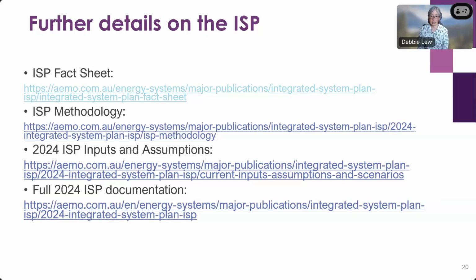That's right. So when we have our subregions and those interconnector paths, when we pre-calculate what the limits and the flows are, and when we apply an upgrade, a lot of the time it won't be a single number. We will actually put a constraint in there where it's not as radial or is more mesh. So we'll have distribution factors in the constraints which represent the change, and that's part of the reason why we have to do one in, one out type studies where you put transmission in. What's the impact on the economics of the system when we do that, rather than trying to have the model optimize all these augmentations at once. So it is a manual process. That's why we have so many iterations trying to get those aspects correct.